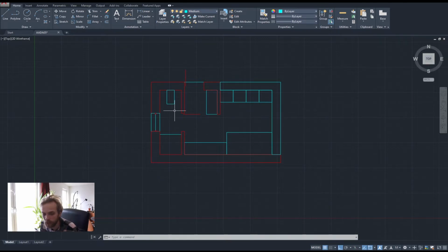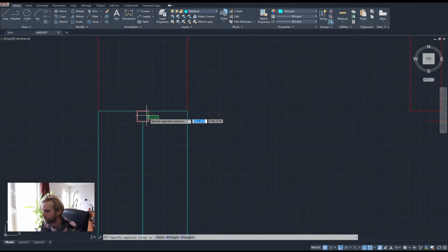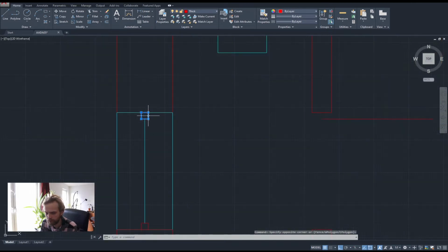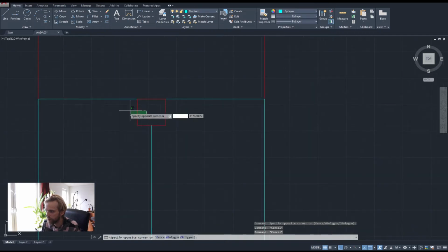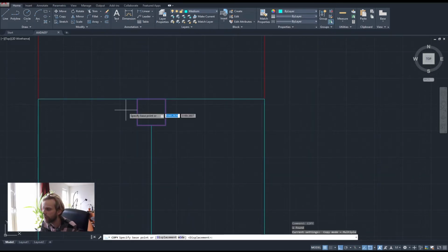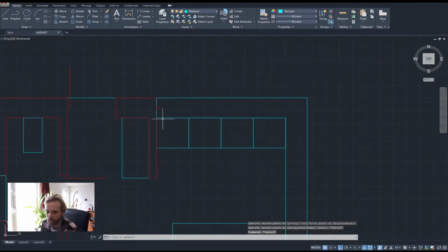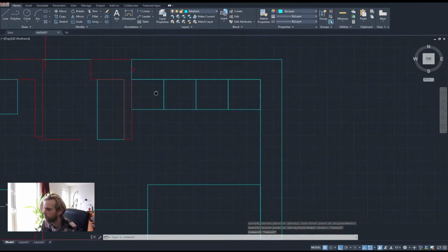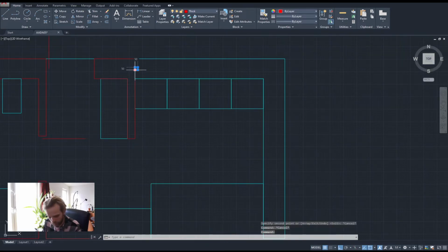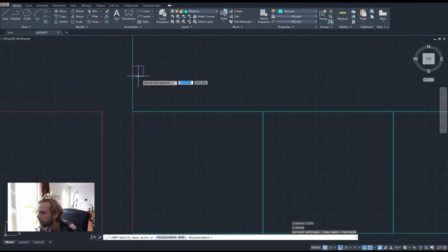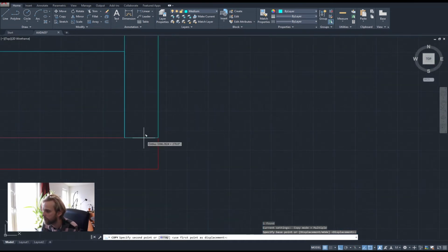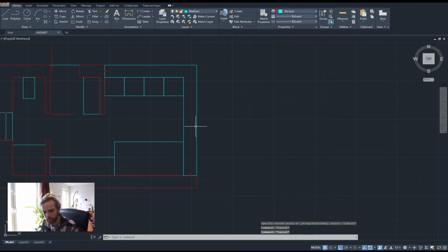Now on to creating the window frames. To do that, I will be reusing this window frame cut here. So I'll just copy it from the side midpoint right here to the midpoint right here. There we go. That's one frame that's being cut. I'll also make a copy to the other side of the window from the bottom midpoint here to the midpoint here. Like that, right?